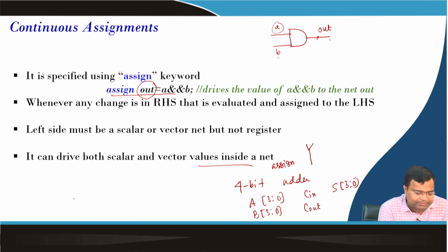So, in the assign statement we can write assign {Cout, S} = A + B + Cin.